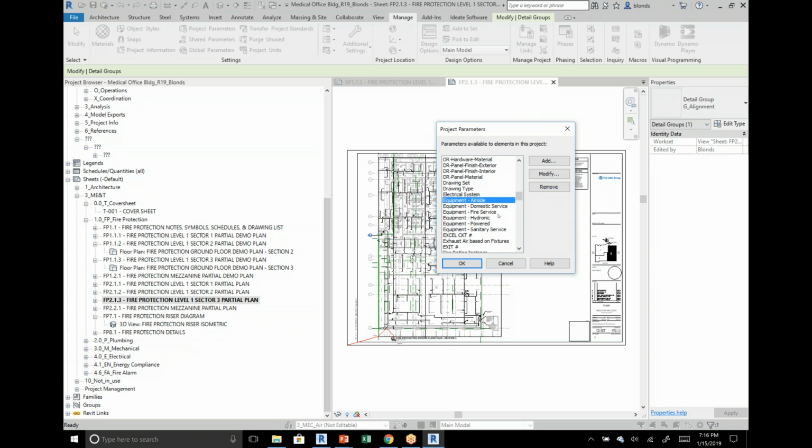Those parameters will hit any mechanical equipment category family that comes in. So regardless of if I'm using my own family or some third party's one, as soon as it enters my program, it will get the same filter capability. So that's a nice way around if there's some trade-offs, if there's some issues with, well, will it have this parameter I need? You can set it up this way and know that you will get that workability. Does that answer your question well enough? Great.